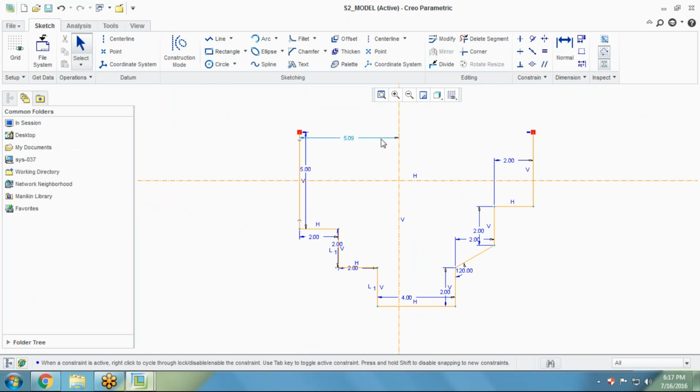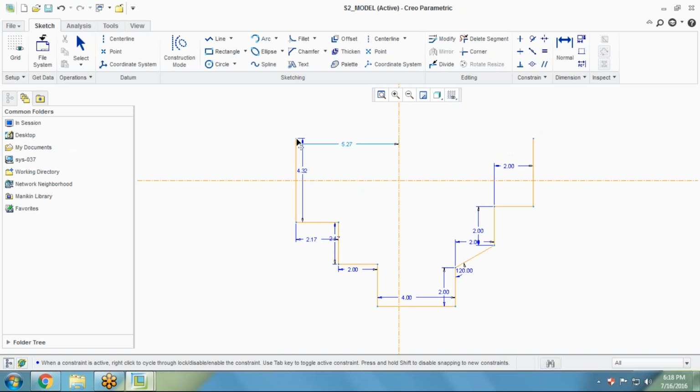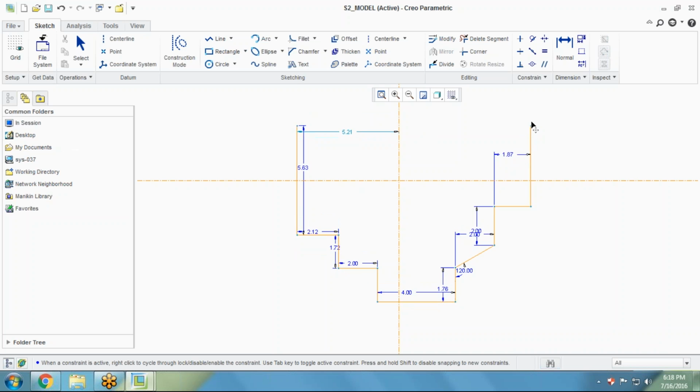Now what is needed there, the initial thing should be given. You can see there, this is the line, but we have not specified any distance for this line. So how is it constrained? You can see this is a sign showing a strong horizontal alignment constraint, meaning this is creating alignment with the initial line. So if I change the value of the first one, the other will change automatically, because these are correlated. If I change one, the second one will automatically change.